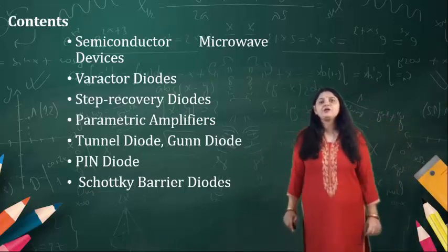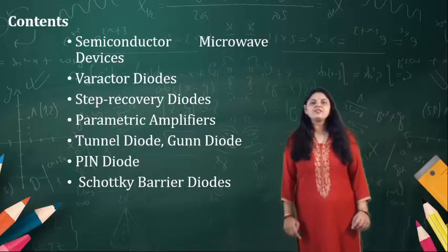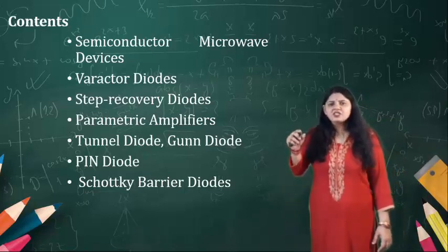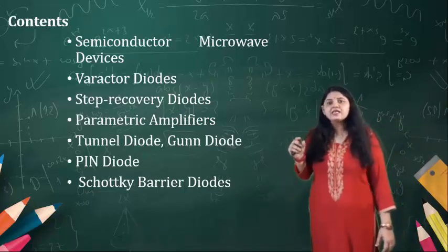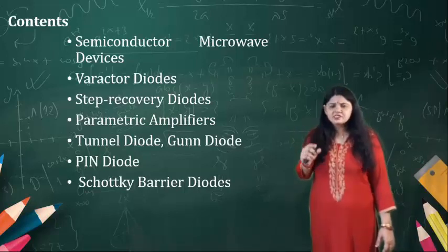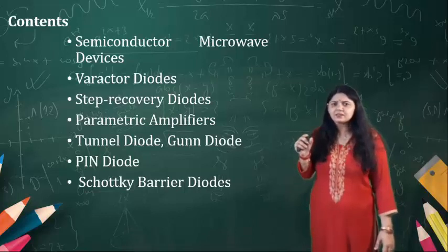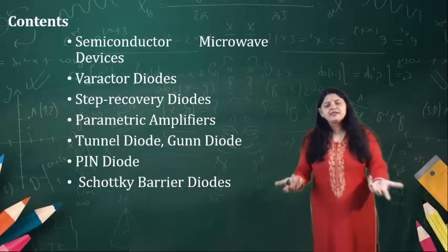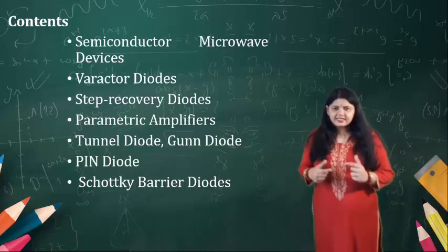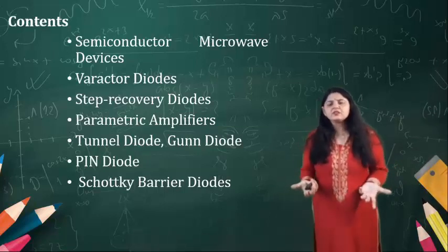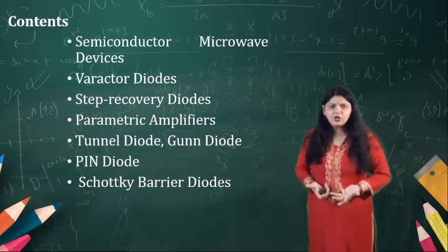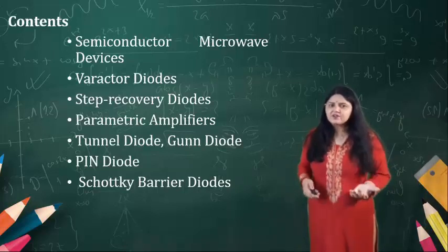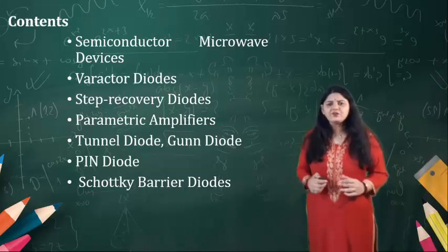Now we are talking about the microwave frequency. So the frequency is high. As the frequency is high, the semiconductor junction has to be made thinner. As we know, when the junction is thinner, it is very difficult to obtain high power. That is why the difficulty is there. So we need to go for something which does not depend on the junctional property of the semiconductor material. That is why it is divided into two different parts.